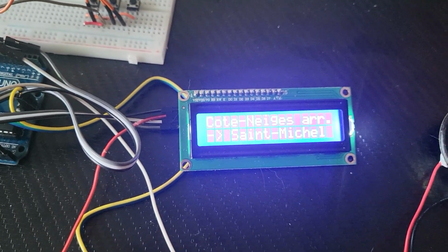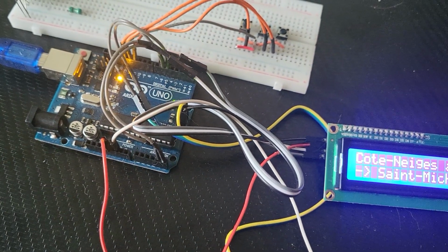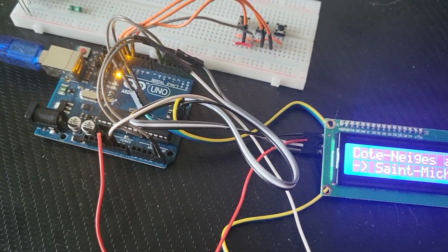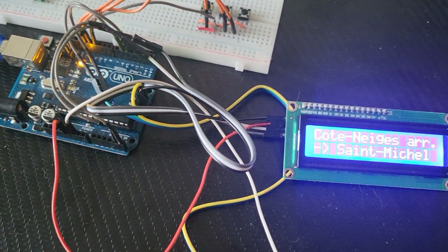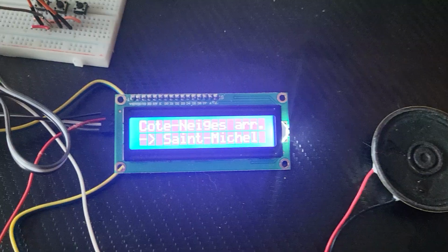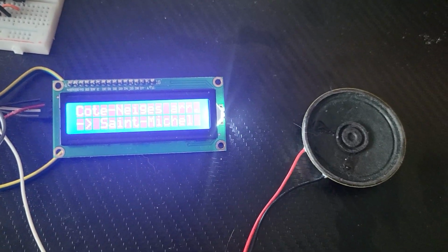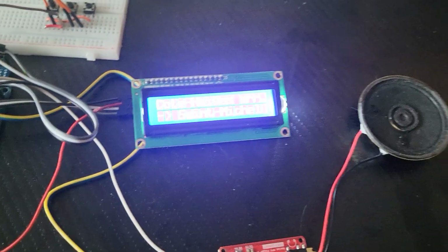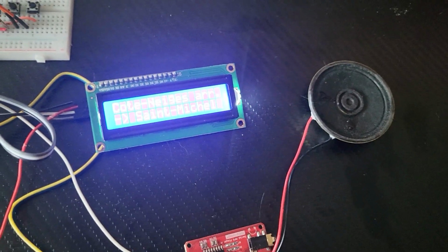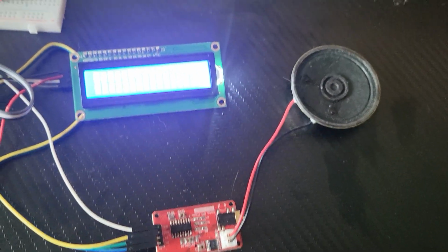because when using the hardware serial and having the Arduino connected over to the USB, it will sometimes refuse to upload the actual program to the Arduino if there's something connected to the hardware serial pins, which is why I had to switch to using the software ones. And while it is a bit slower than using the hardware ones, here I don't think speed matters that much because I'm just playing audio off an SD card.